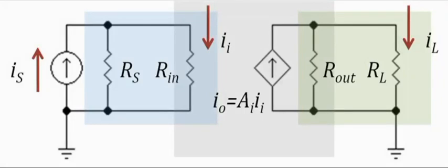Okay, so this circuit shows an equivalent circuit for a current amplifier. Is is the source current, or an input current, that needs to be amplified. Its direction shows the direction of this current, and this current source has its internal resistance indicated by Rs, which is in shunt with this Is.